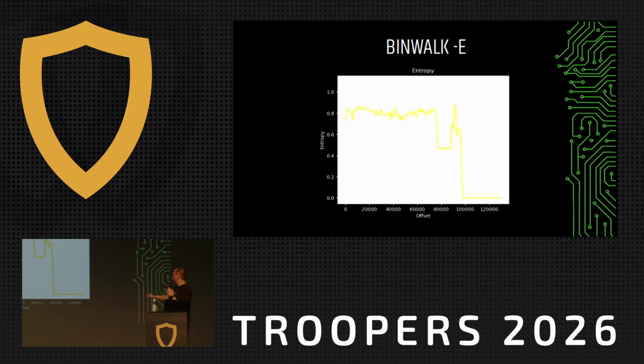Now you can see that the firmware ends at about 90 kilobytes there, and 0.8 entropy. Entropy is basically a measure of randomness. 80% entropy usually indicates machine code for ARM, right? So we have a bunch of code at the beginning and a bit near the end there. Then at 0.6 entropy, we have strings. This is usually English text, and we have two places, just before the last spike and just after the last spike. That's where we have text, and it's quite a lot of text.